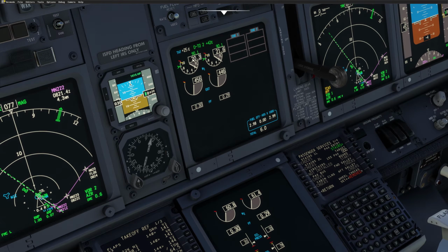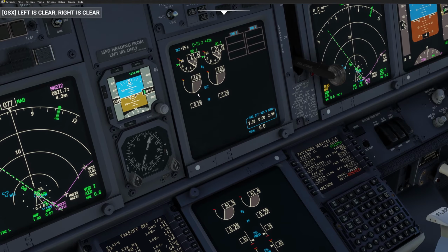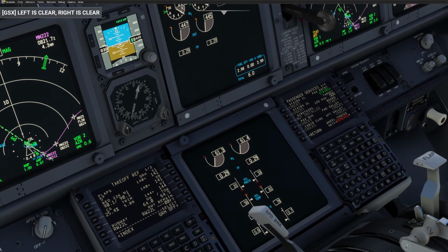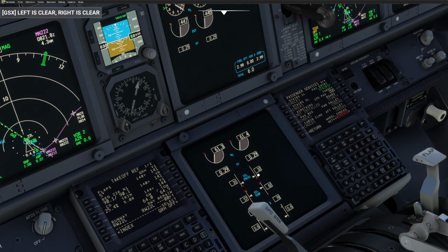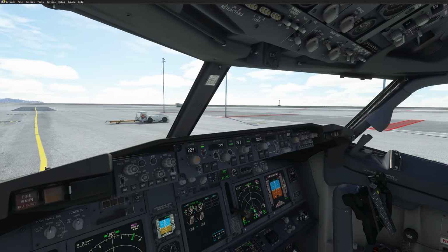The figures you should see are around 246. You can see 20%, around 400 degrees, and 60% N2. So 2, 4, 6, and oil pressure is around 30 psi. It should be out of the amber position as well. Sometimes the oil temperature might be low, especially in winter, so that's normal. You can expect the engine to warm up within a few minutes. All engine parameters normal. Let's do the after start flow.